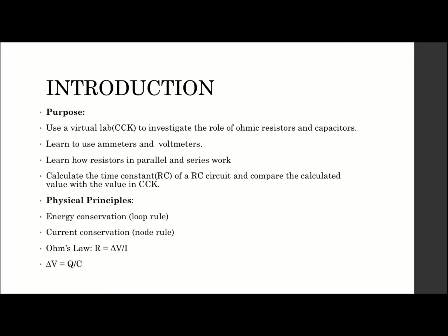The physical principles that I used in this lab are energy conservation, which is also called the loop rule, and current conservation, which is also called the node rule. I'll also use Ohm's law, which is R equals delta V over I, and also delta V equals Q over C, in which C is the capacitance of the capacitor.